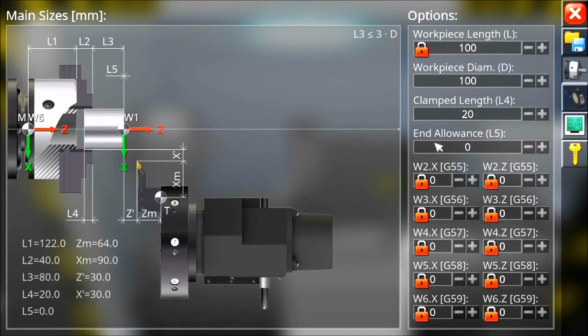Normally the workpiece 0 is set 2 or 3 mm inside the workpiece, so that 2-3 mm of blank will be removed to have a complete machining. Normally these are workpieces that are either rough in crust or cut with a hacksaw, so it is advisable to machine them right to the center.